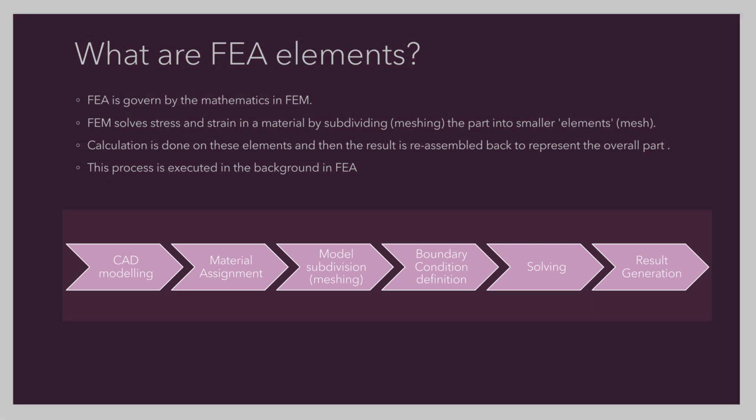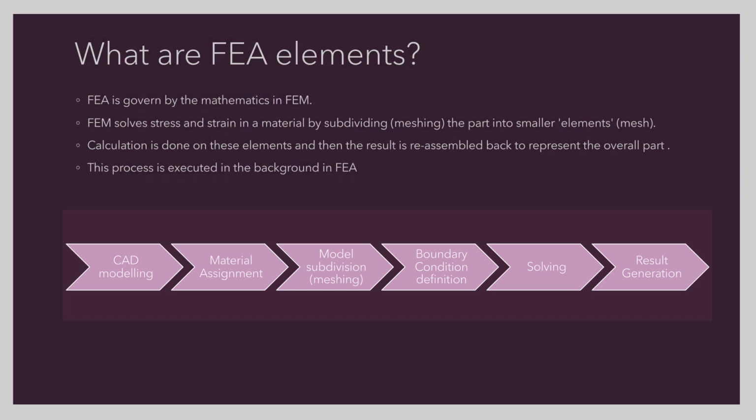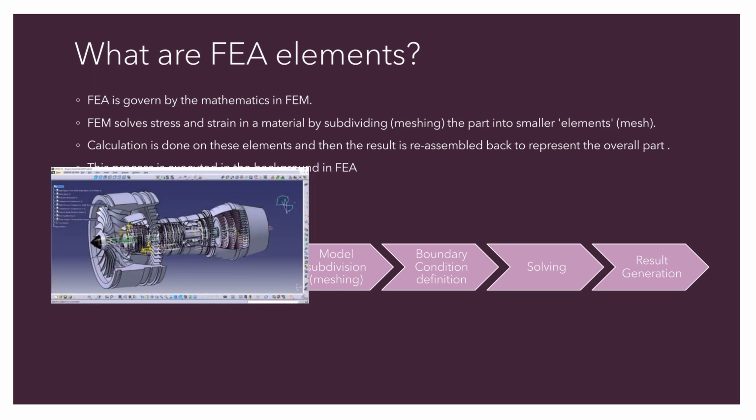The following diagram illustrates the FEA process for a typical linear static analysis. We start with our CAD, where our CAD contains geometrical information regarding the part to be analyzed. Here we would determine the appropriate element type that can capture the part geometry as close as possible.